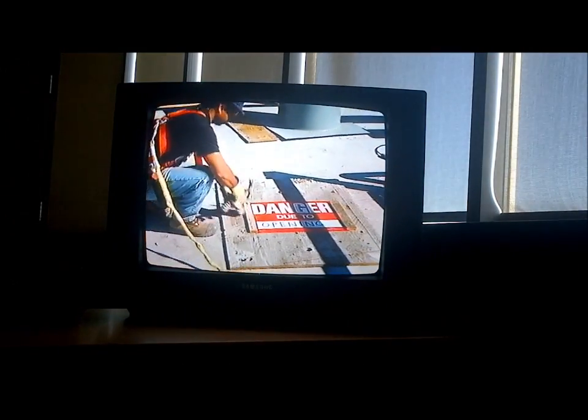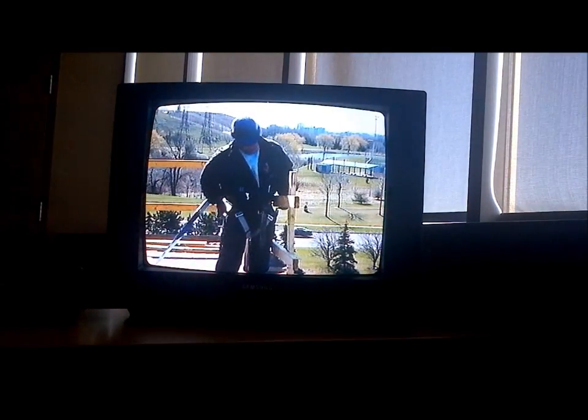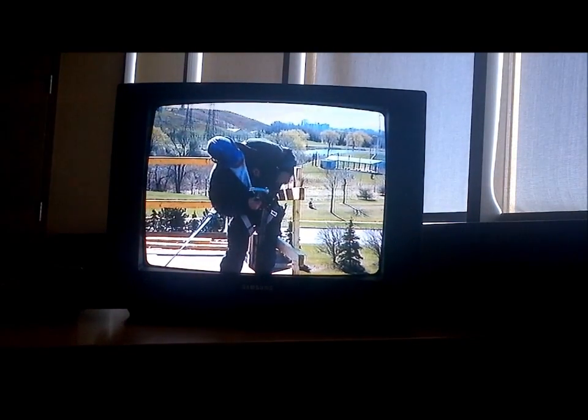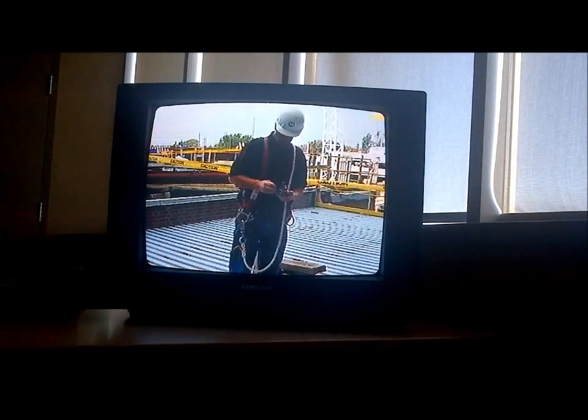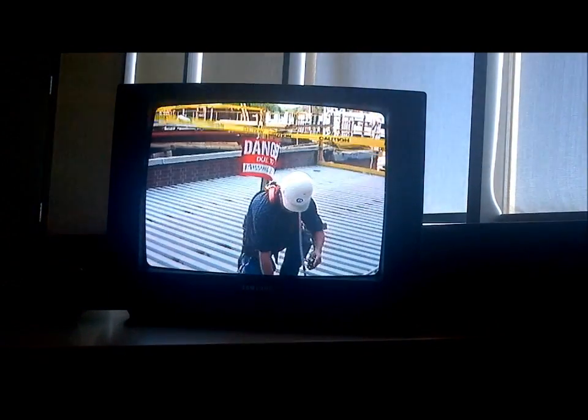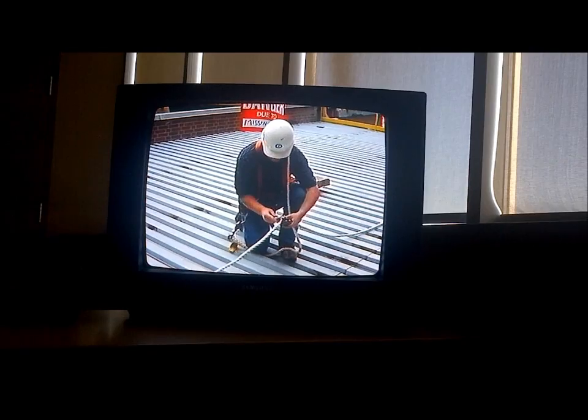Materials used for fall prevention must be adequate for the purpose. For example, covers over floor openings and guardrails must be designed and installed to comply with regulatory requirements. When guardrails or covers are temporarily removed, access to the hazard area must be restricted and proper warning signs posted.